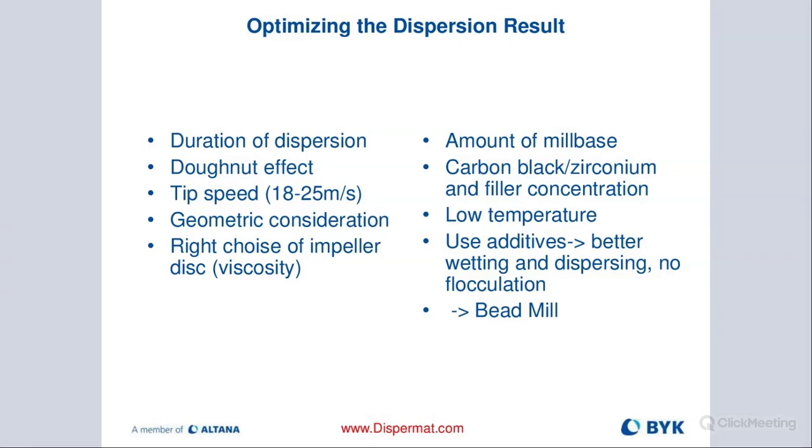Now, there are going to be cases where obviously a donut doesn't form, but you're still pre-dispersing. That would be if you're dealing with viscosities that are very low. That would mean that the donut wouldn't be able to form because it would collapse as soon as it's trying to form, because your viscosity is very low.